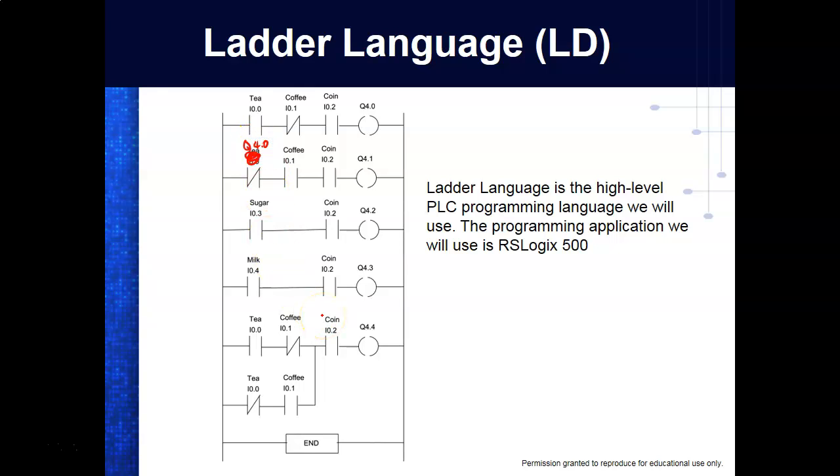Well, that's not an input device. This is a simulated contact that's being controlled by this coil. So when this goes true, not only does this come on, this right here would also cause this contact to change states. And like I said, we'll look at these. So that contact would open.